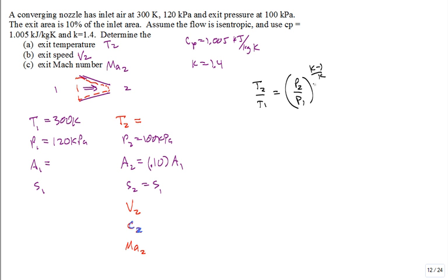You know the ratio of the pressures, and you know the temperatures. Guess what this temperature T2 comes in at? 284.8 Kelvin. Colder. Went from 300 down to 284. Okay. How about the next one? How do I calculate V2? It won't be as easy.